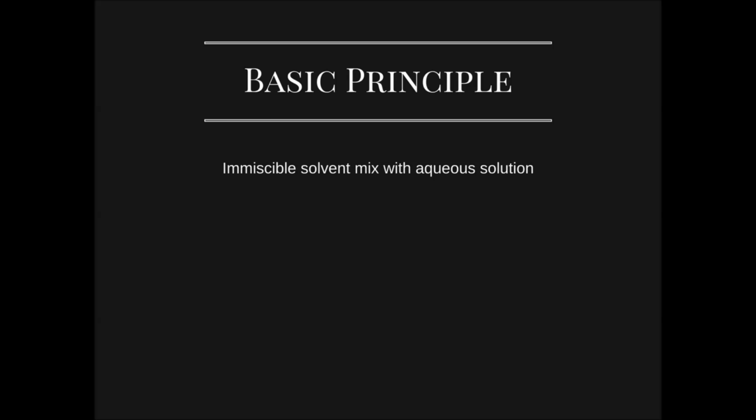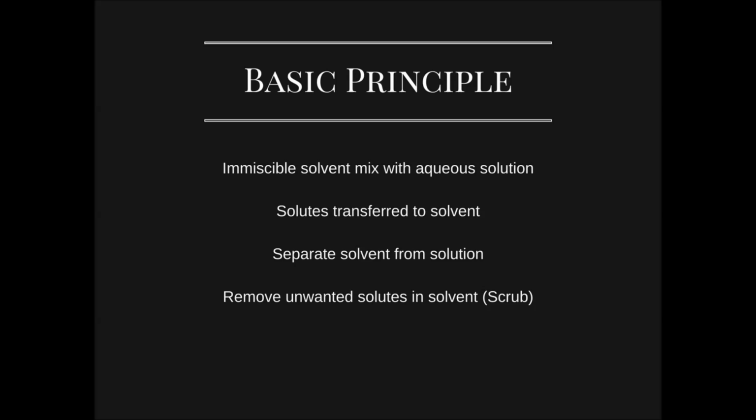First, we will mix our solvent with our aqueous solution or our sample. Even though naturally they are not mixable, through physical forces they could be dispersed into smaller particles and get into contact. The solutes will be in contact with the solvent, and the solutes will have higher or stronger bonding with the solvent compared to the base. So, the solutes will be transferred to the solvent. Next, we will separate our solvent from the solution through the density difference. The solvent will be above, and the solution will be under. We can remove them and separate them into two compartments.